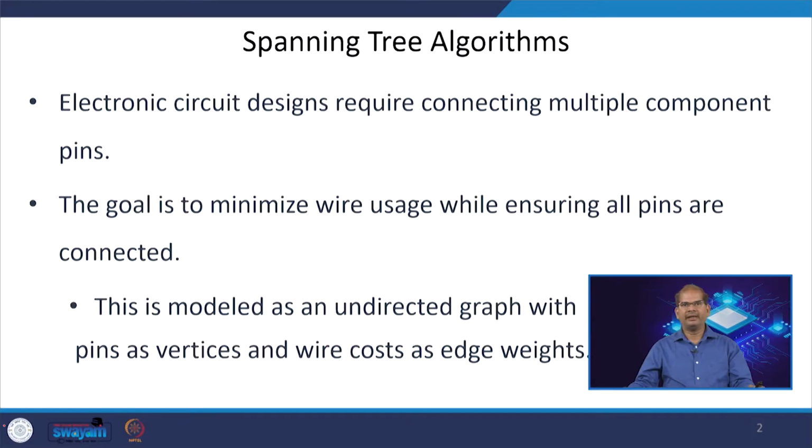So, we know that electronic circuits consist of multiple components, and they are connected with wires or interconnects. There is always a tendency to optimize or minimize the wire length inside the design. There are several algorithms, but the spanning tree algorithm helps us minimize the total wire length inside the VLSI circuit design, and that is useful to reduce the interconnect length, which in turn reduces the delay